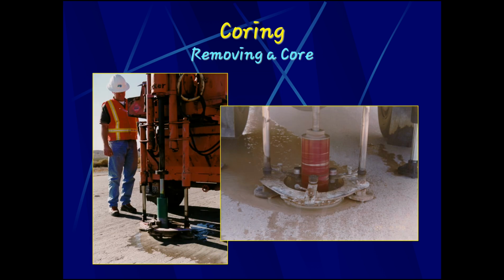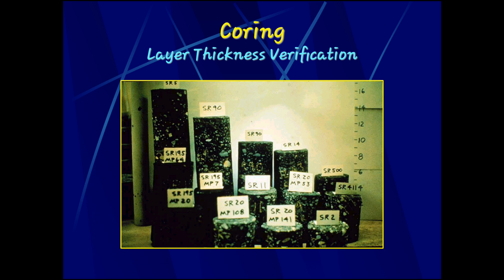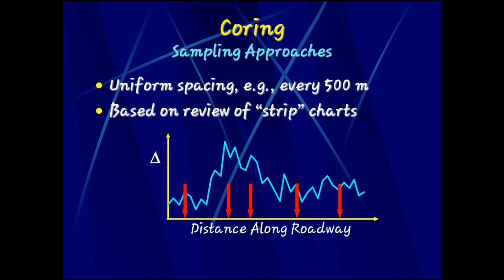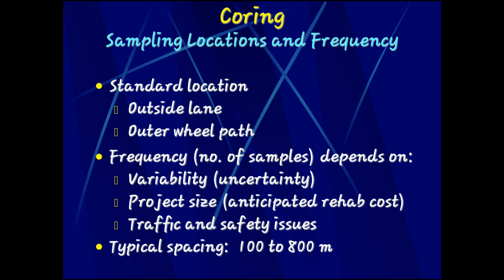So here are pictures of removing a core, the thickness verification using coring, and the distress cause identification. So here are the sampling approaches of coring.